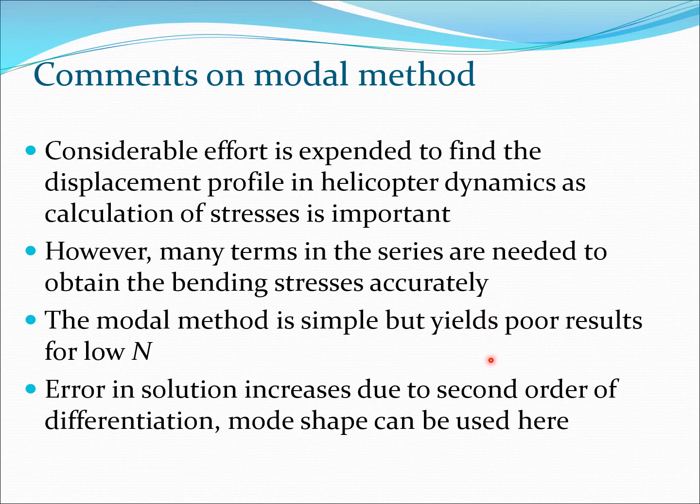Now the modal method is simple but can result in poor results if this number of terms in the series is low, and the reason is that the error in the solution increases because we are taking the second derivative of the mode shape function, and this essentially will amplify any kind of numerical inconsistency which is present in this solution.